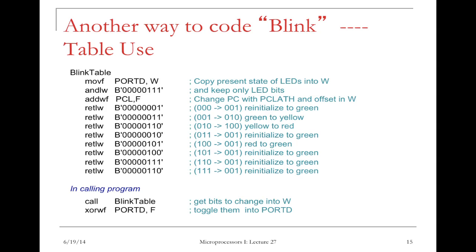Okay, now we get to this instruction. What do we do in this instruction? This instruction is RETLW. So when the microcontroller executes this instruction, it will put this 011, of course the upper bits are 0, into the working register, and then return. Wait, that's just two things.